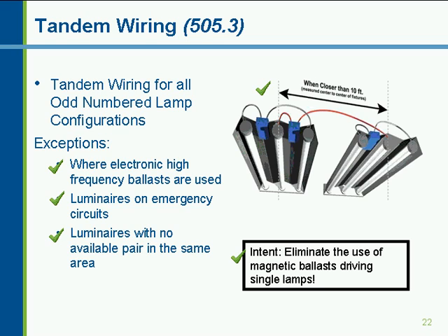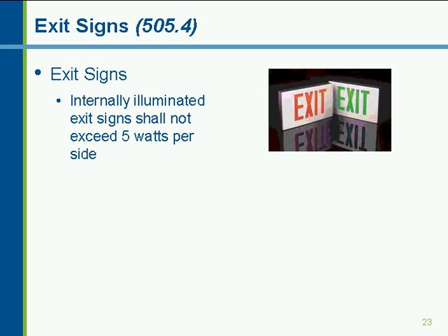Again, this only applies to magnetic-type ballasts when you have a 1 or 2 lamp ballast driving just one lamp. Not a very common application today, but sometimes you will run into it. One other specific requirement on exit signs, there is a limit of the wattage.